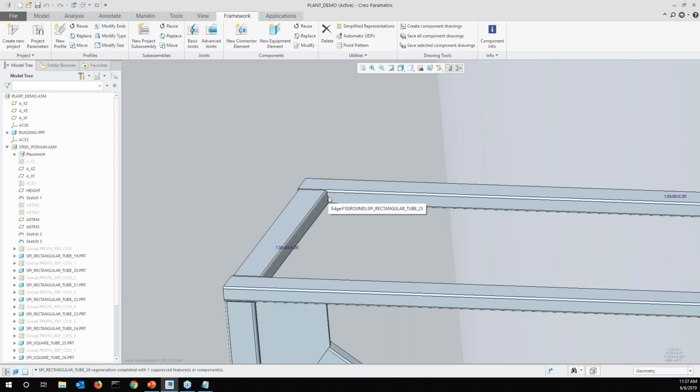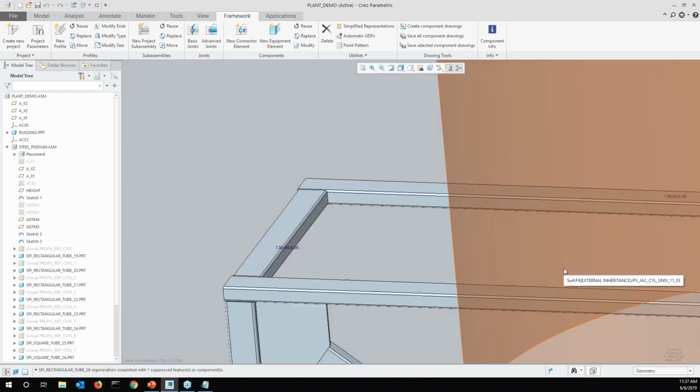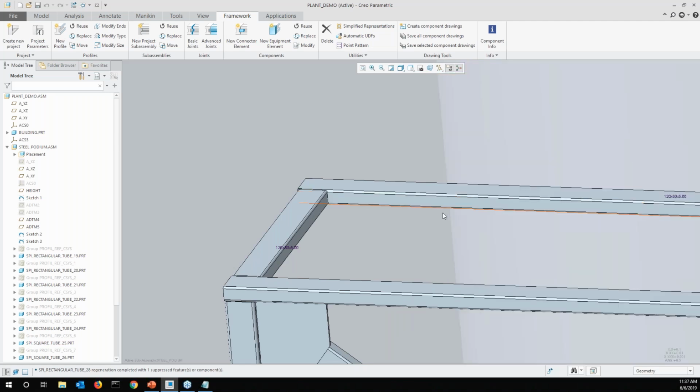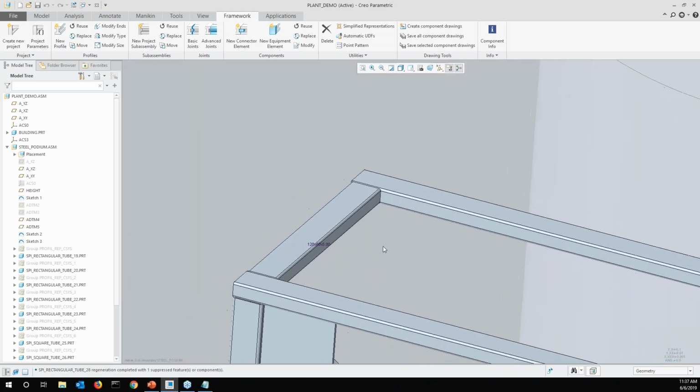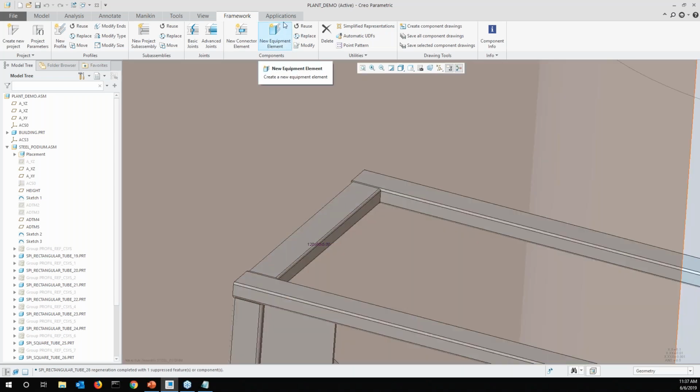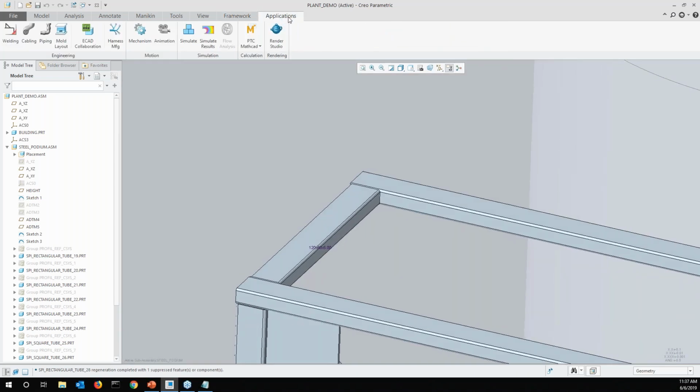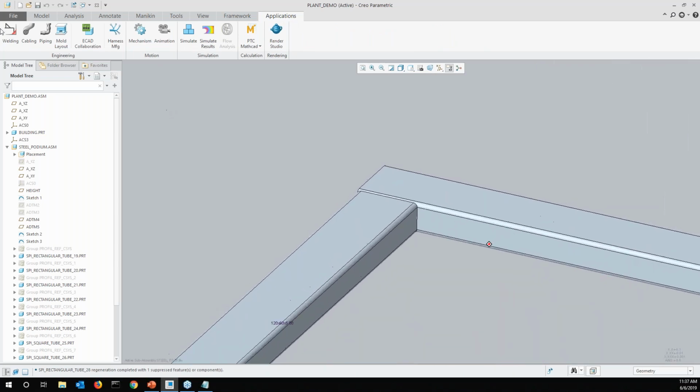next thing I've seen people do as well is start adding weld elements or weld features. So if you're not using bracing or bolts or connections, you can also tag this extension with the weldment application. So if I jump over to applications here, this is already included within the base Creo license, so everyone should have access to this welding feature here.